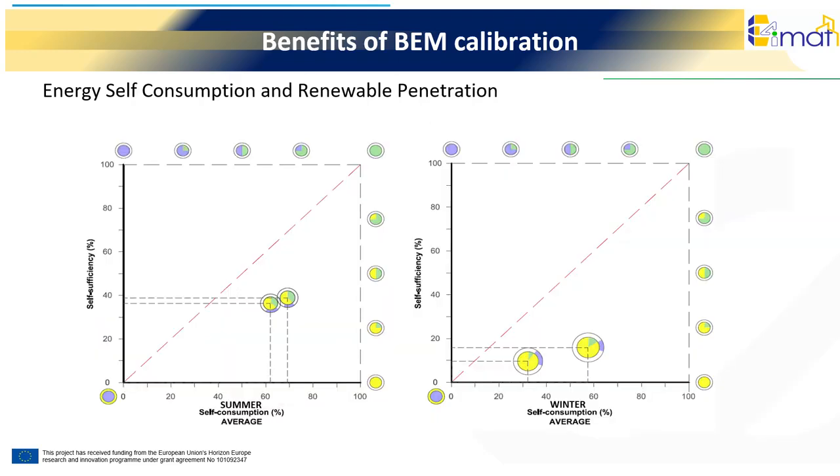Furthermore, calibrated BEMs can help to establish new energy-saving strategies that aim for the decarbonization of the building sector, including photovoltaic plant, PV, sizing, design, and optimization. For example, a calibrated BEM can be used in the optimization of the consumption of a building's own PV production, self-consumption. Where a demand-side optimization strategy of the building's thermostat and thus, its heating and cooling load, can assess the level of improvement in self-consumption of its PV plant.